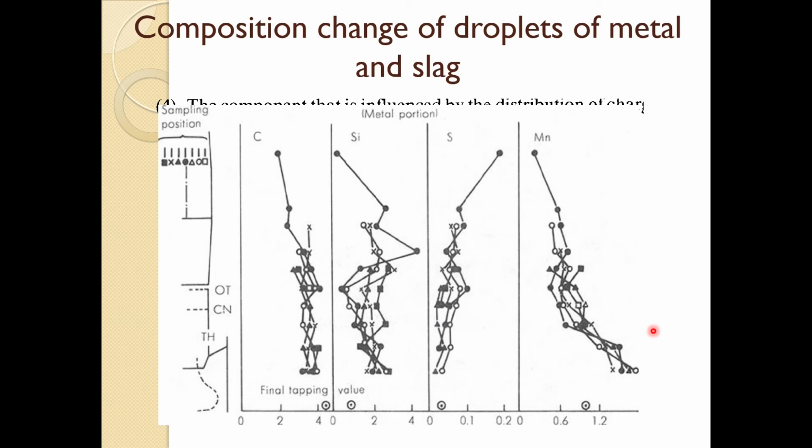This gives an idea of how the situation prevails inside the blast furnace, and how one can improve it. Nowadays, in fact, you won't find silicon percentage that high. This is again, as I said, a minimum 4-decade-old dissection study. So, many improvements have occurred, and silicon goes very low now with the preparation of proper raw material and temperature control and other things. Now it can easily go to 0.5% or so.